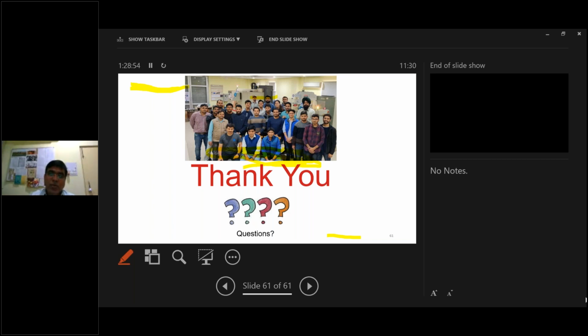Now, say for example, I am doing some additive manufacturing, and based on it I have some input parameters and some output parameters. Say the case you referred, which was done by an MTech scholar. He used the FDM technique only, with PLA, or I don't know exactly whether it was ABS or PLA, with some kind of reinforcement. Yes, sir, carbon fibers in carbon PLA, sir. Carbon fiber layering was done, and then we tested it. If I put that carbon fiber direction in one particular direction, or at a 45-degree angle or 90-degree angle, I print those and test as per ASTM. If I have this data, I can use it further in a model and predict that if somebody does it this way, these are the input parameters and these will be the predicted property. So that is machine learning.